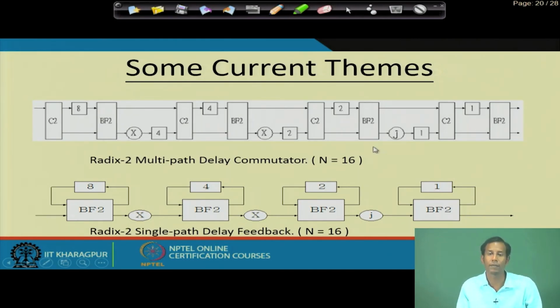If we use the pipeline technique, the area requirement will be higher, but we can achieve a very high operating frequency, and the computation time for that FFT processor will be much lower. For applications like designing an OFDM processor, in the OFDM transceiver we need the FFT and IFFT block to run in the gigahertz range.